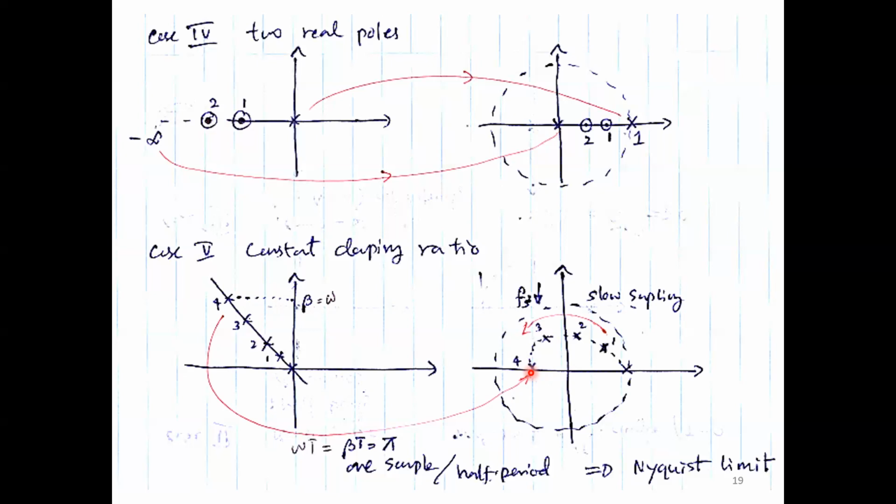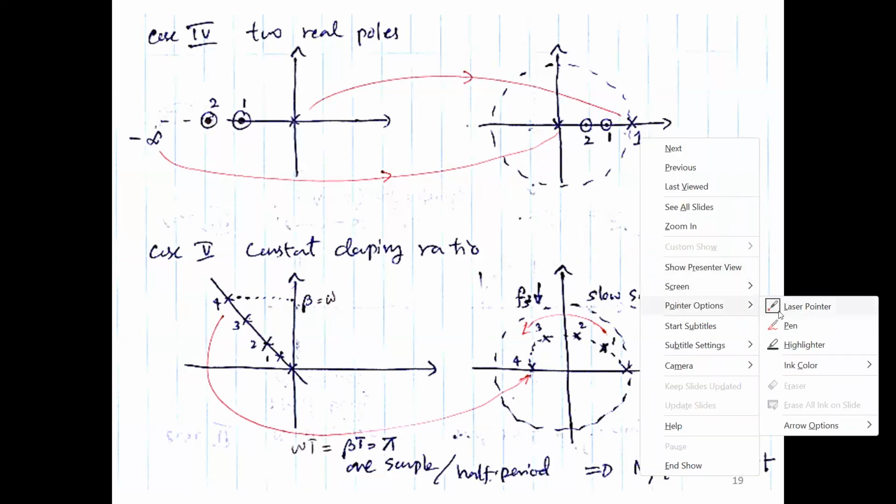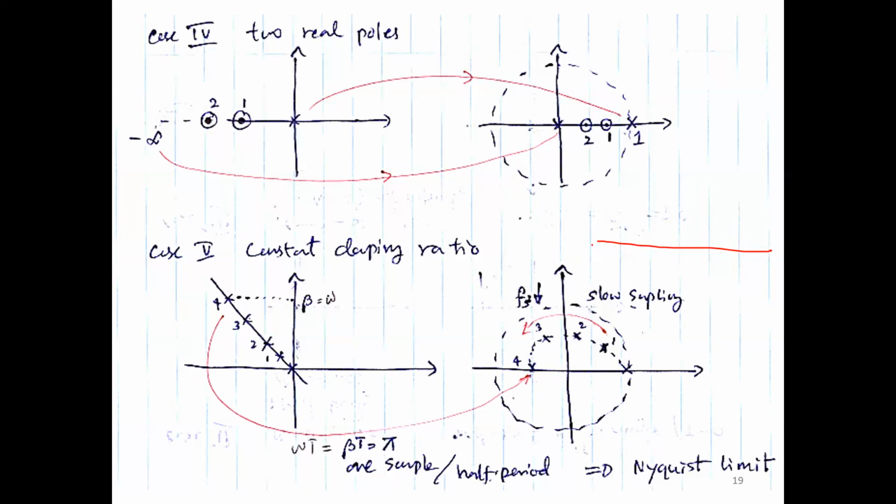So if you further reduce your sampling, you enter this area, where this angle is more than 180 degrees. Then your samples will not represent the original signal at all. Suppose it's a sinusoidal waveform like this, and you take your first sample over here, and after 180 degrees maybe you are over here, but you don't take a sample even at that point.